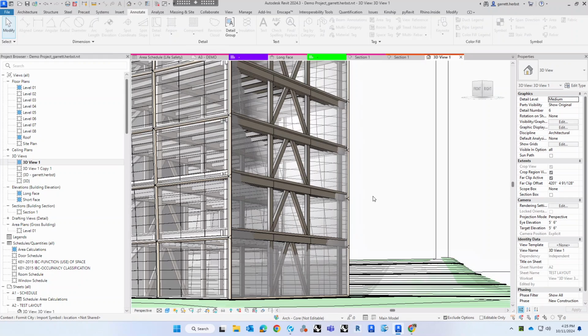Now, the pain of that form is just the curvilinear nature of it and the amount. But we expose exterior CLT and glulam all the time. It's just the way that you have to break it. Depending on the environmental conditions, you either have to truly break it or you do different things to wrap it and protect both inside and outside.